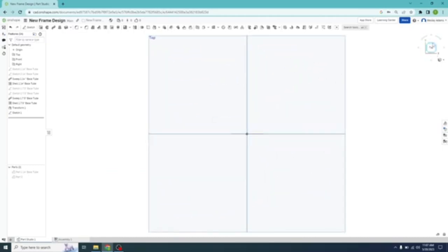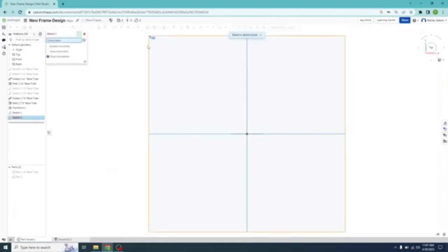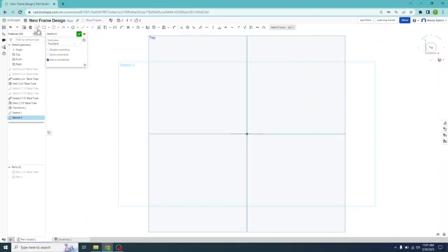We're going to create a line. So we're going to create a new sketch, select the plane that we're in. We're going to go to the line tool. We're going to draw this out. Now we need a right angle. So left click in the center of the plane, draw that out, and then left click again, drawing it across, and then left click, and if you draw out the mouse, it looks like it's creating another line. Hit escape, go up to the dimension tool, set our dimensions.